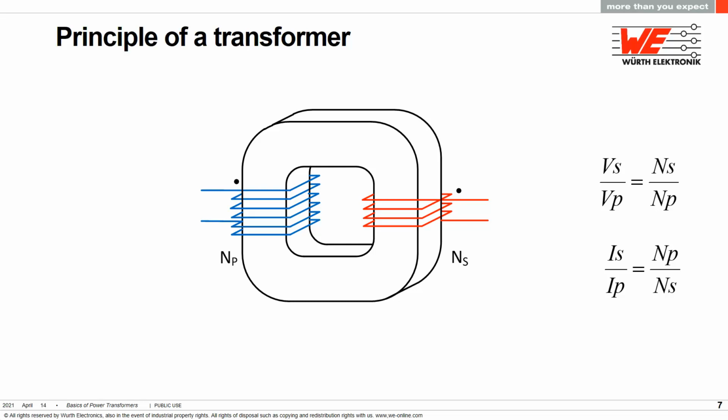The flux, voltage, and turns are linked by Faraday's law, making voltage proportional to the turns. With this, we can boost or reduce voltage simply by changing the turns of the secondary. Because energy cannot be created or destroyed, in the ideal case, power coming out of the transformer must be the same as going in. Therefore, the currents in each winding change inversely with the voltage. This flexibility allows us to design a low voltage, high current welding transformer or a high voltage ignition coil using the same principles.